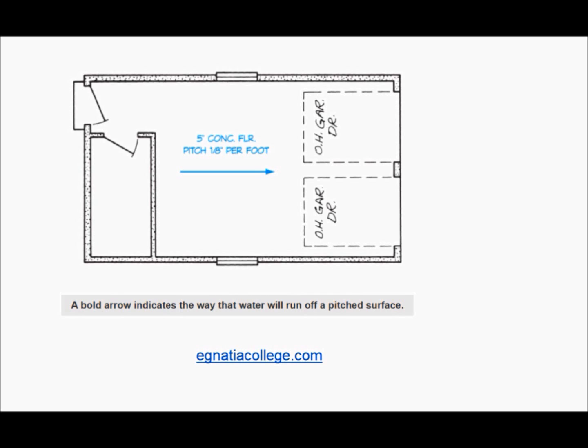This requires detailed coordination between the electrical installer and the other utility installers prior to starting the installation of the utility systems. The electrical installation must be laid out around the other utilities, with the other utility layouts normally having priority. The other utilities to be coordinated may include plumbing, fire sprinkler, heating and air conditioning, and specialty systems. This coordination must be done for both the underground and above-ground systems.